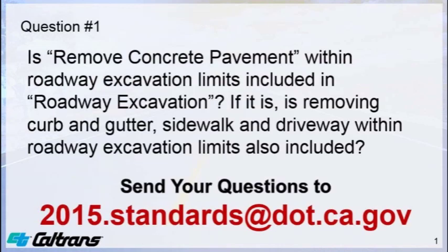Okay, we're going to start with the questions now. I'm going to direct that question to myself. The question is: is removed concrete pavement within roadway excavation limits included in roadway excavation? And the answer to that is, if it's within the limits of roadway excavation, concrete removal is included in the item. The second part of that is, if it is removing curb and gutter, sidewalk, and driveway within roadway excavation, is that also included?